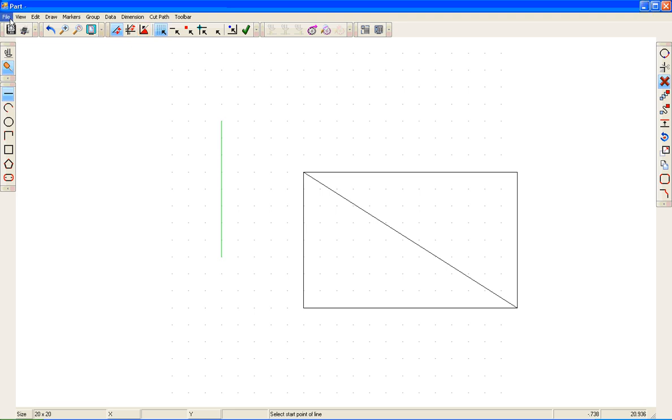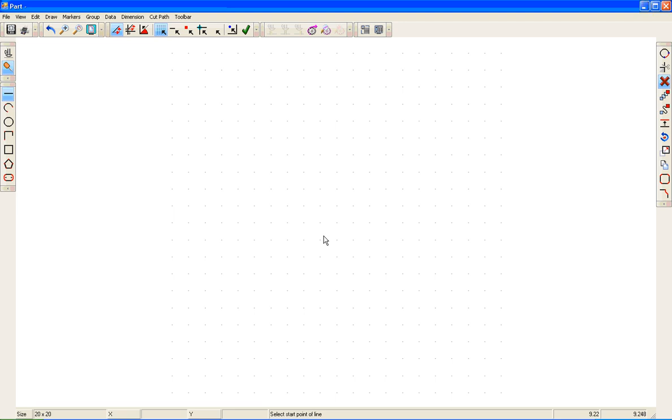Let's go ahead and clear the drawing. Now we are going to talk about the different input methods. One other thing that I did fail to mention: the snap icons are always used with your mouse. The different input methods, relative, absolute, and polar, are intended to be used with the keyboard. Now, all day yesterday, I worked in relative. Relative is by far the easiest input method that we have.